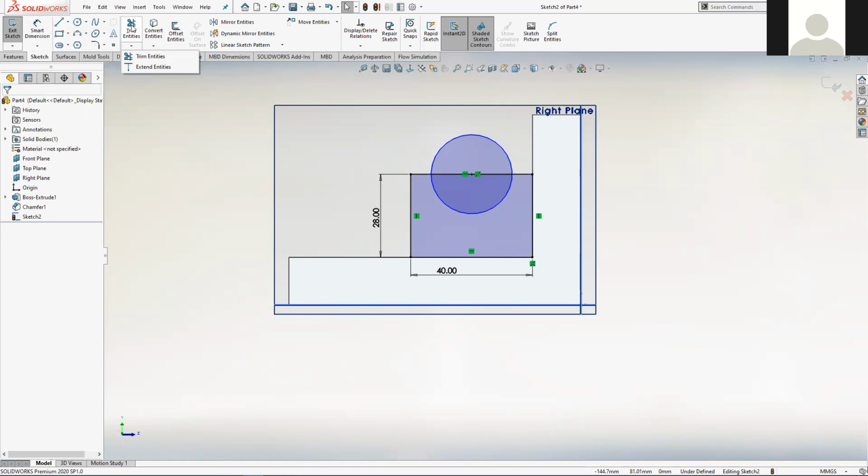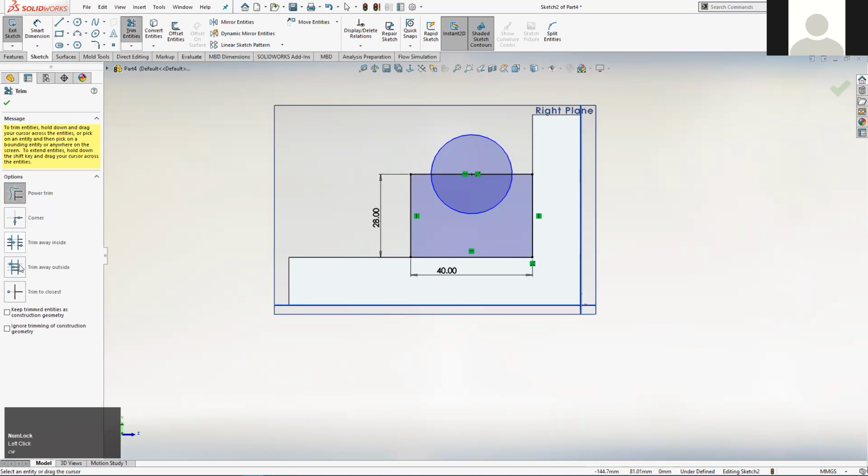So just click on the scissors, and you get this dialog that allows you to tell the system what type of trim tool you want. The one that we want is Power Trim, and it's arguably the most flexible method of trimming geometry. And all you do with this, so I'm going to do it in some free space over here first. I'm not going to use it properly on my geometry. You literally just click and hold with the left mouse button and just draw a freehand line.